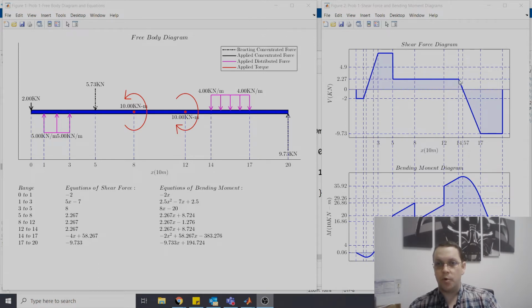So we have a lot more shear happening. And so the highest overall order of magnitude for the shear is down below. You can click on a couple of points anywhere in the graph to figure out what values you're at. So a swing from plus 8 kilonewtons down to just shy of 10 kilonewtons. There's about an 18 kilonewton span from one side to the other. Again, it goes back to 0 over here where this particular end is supported. So very interesting geometry.